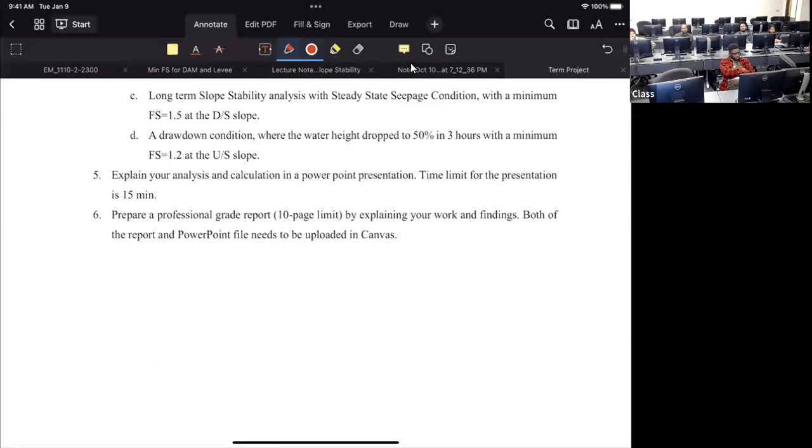So how can you get the ratio? The solution is there. Everyone knows the solution. All you need to do is add something to the system. You need some piping, some pumping station, right? You need to add a detention pond within the system. As long as you can add the detention pond and store the water whenever the peak flooding condition is coming in, you are solving the problem.